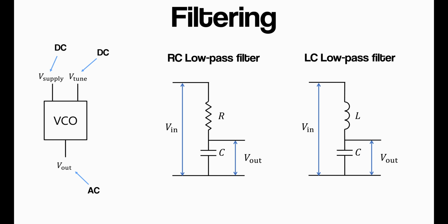One thing to be aware of, if your tuning voltage does go through a low pass filter, when you're carrying out the cavity sweep, you have to carry it out very slowly, because you could intentionally be changing your voltage, but because you're filtering it so heavily, the actual time it takes for the tuning voltage to respond will be quite long.